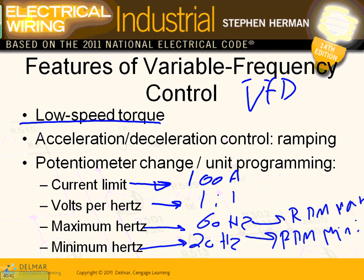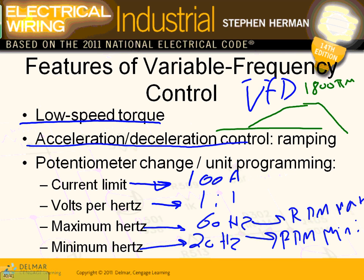Frequency, guys, also does the acceleration and deceleration, the ramping up. The nice thing about them, here's my motor. I ramp up my motor to full speed, and when it's done, I ramp it down. So this is say 1800 RPM, this is synchronous speed, and this is 0 RPM. Everybody knows what accelerating the motor is, bringing it slowly, gently to speed. No inrush, no electrical stress, no mechanical stress.